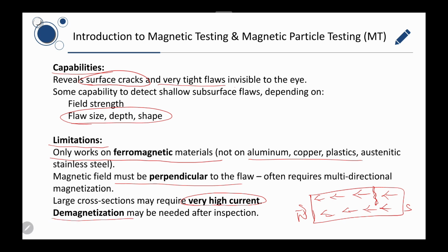Then demagnetization must be required. After testing, residual magnetism can attract debris or interfere with the component's function. Demagnetization is often required before the part is returned to service. Understanding these capabilities and limitations helps ensure the right NDT method is chosen for each inspection task.